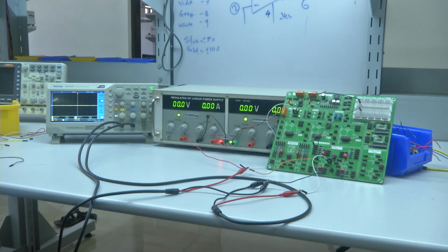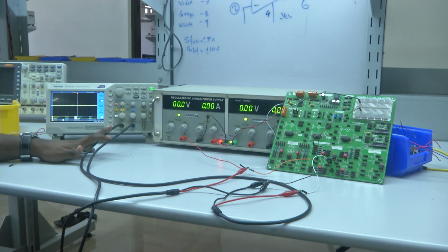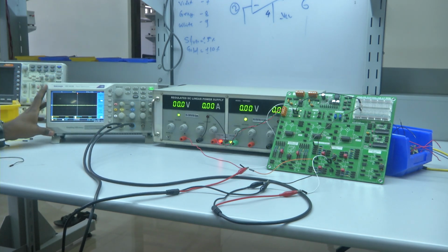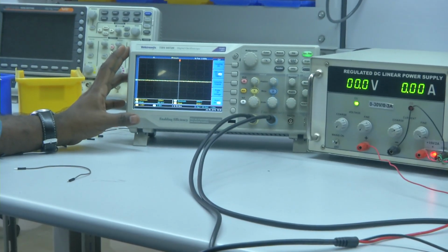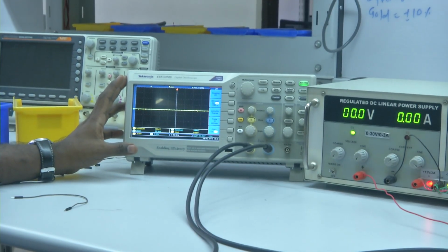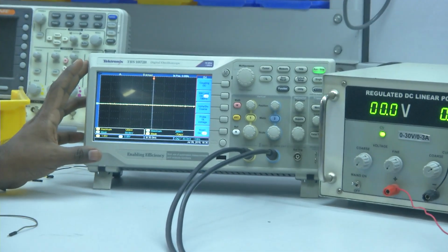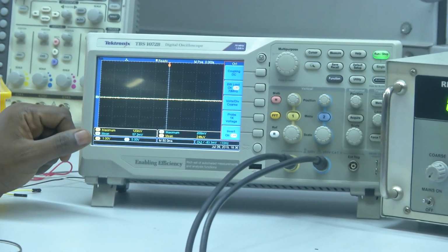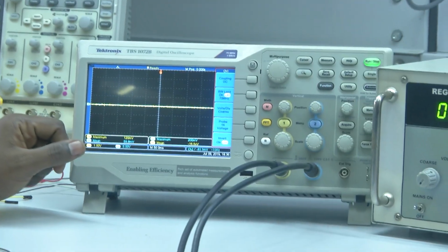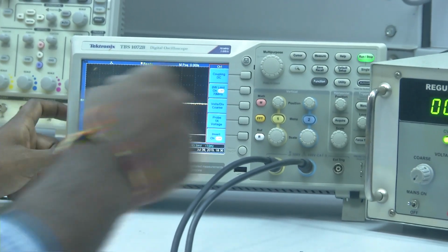Let us see the working of the board. Right. So, let us focus on the oscilloscope. We will try to increase the input voltage in steps of 100 milli, 200 milli, 500 milli and 1 volt, in the same way as we saw previously in the inverting amplifier configuration, and we will observe how the output is also changing. The output by input gives you the gain, and we will calculate the gain.